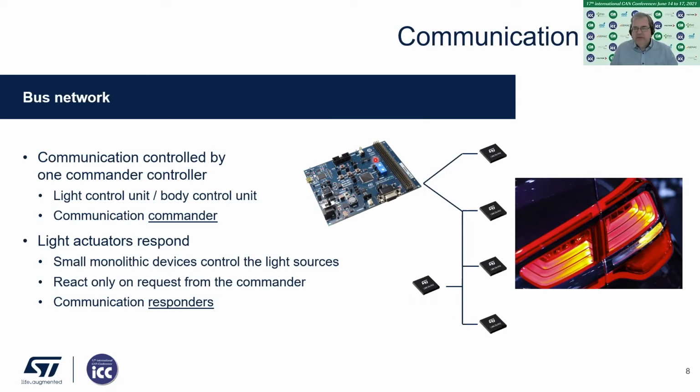And then the bus network has another advantage. Whenever there's a message sent from the domain controller to the bus, this message, or this frame, as we used to say in CAN, is received by all of these drivers. So you can be highly efficient when communicating and sending frames to these drivers, which is very important if you want to have an animated light in the rear light, when you want to drive several hundred LEDs.